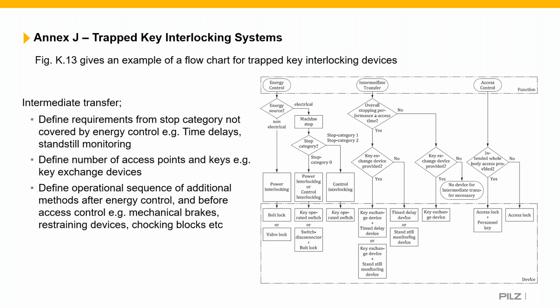We then have the intermediate transfer. So this is taking the key out and putting it in somewhere else. And so we need to look at the overall stopping time and define the requirements based on the stop category that's not covered by energy control. So do we need some form of time delay or standstill monitoring on there or something like that to get the machine into a safe state?